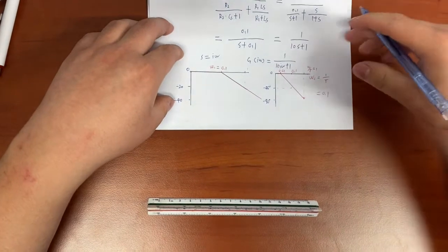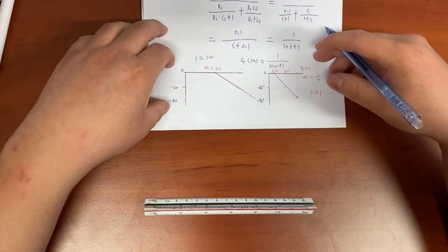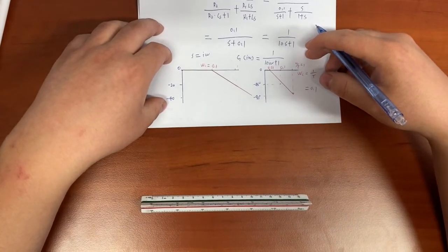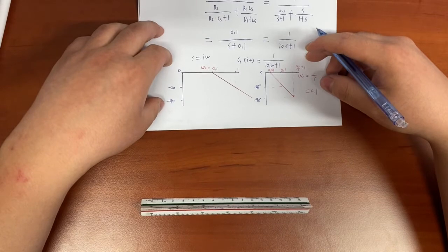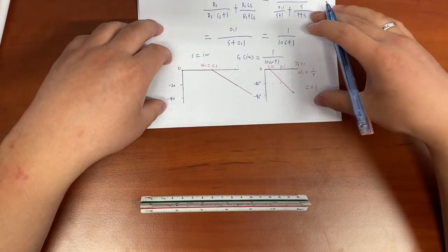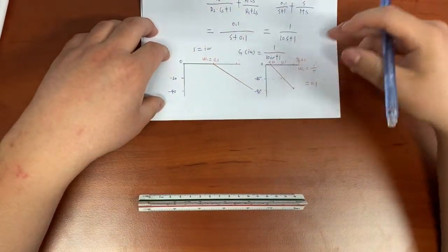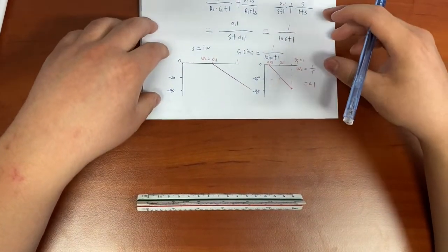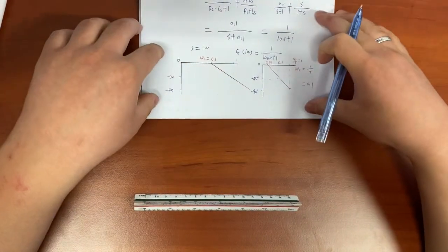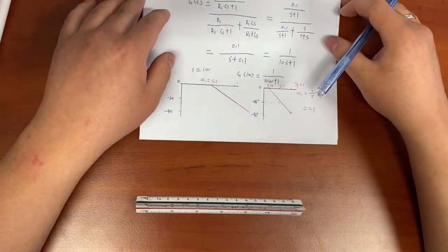As you can see, it's not the actual Bode diagram you draw from MATLAB. We just apply this piecewise linear asymptotic approximation method, and for the exam, in this part you can draw by hand without the semi-log paper. And then let's turn to another case.